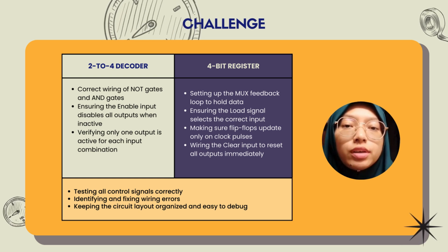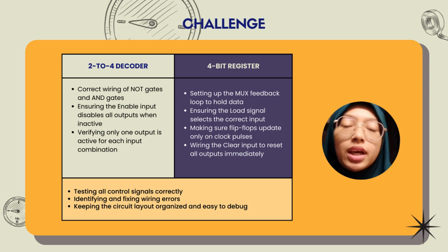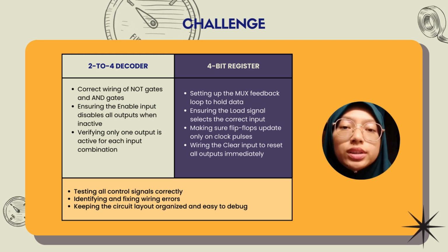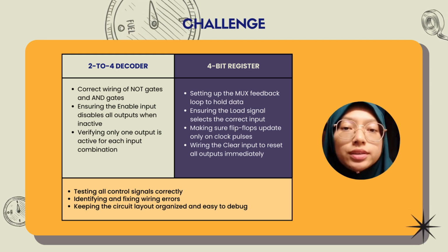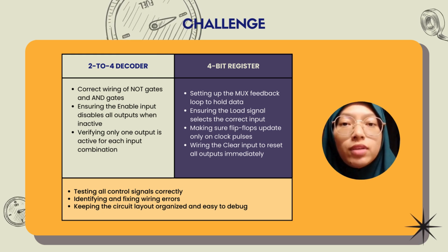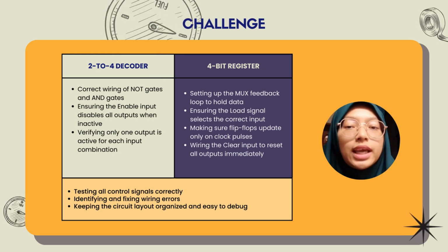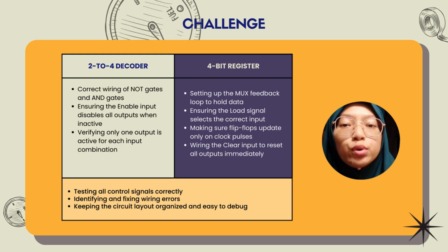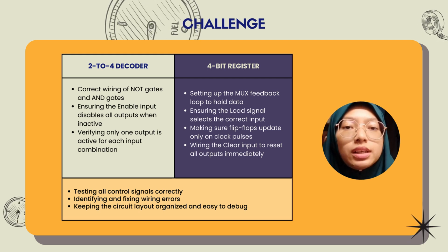And the challenges for the 4-bit register are setting up the MUX feedback loop to hold the data and ensuring the load signal selects the correct input. Then making sure flip-flops update only on clock pulses, and lastly wiring the clear input to reset all outputs immediately.